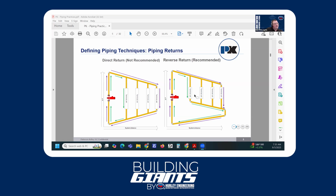We equalize the head loss through each of these branches, and we can essentially self-balance our system that way without using valves and additional pumps. So just keep that in mind as you're in mechanical rooms and boiler rooms. If you see arrangements that look a little outside the norm or overly convoluted, it might be something where they're trying to accomplish a reverse return and balance the plumbing.